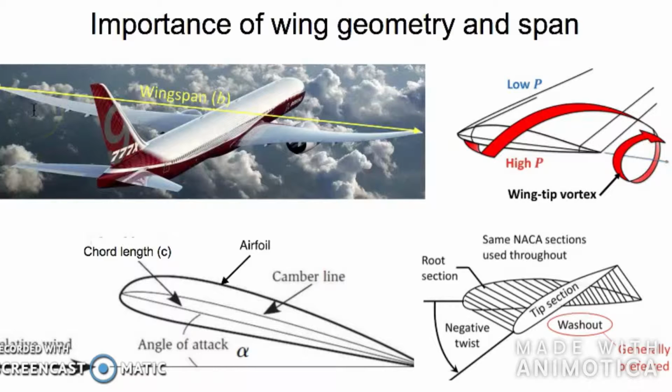When one considers the aerodynamic properties of a wing, the airfoil is not the only thing to consider, since the edges, or tips, of the wing modify the flow significantly, creating counter-rotating vortices at the wing tips, and creating a lot of drag. The geometry of the wing is to be considered as well. For wing geometry, several parameters can be varied. It can be the airfoil, the angle of attack, the chord length, and the wingspan.